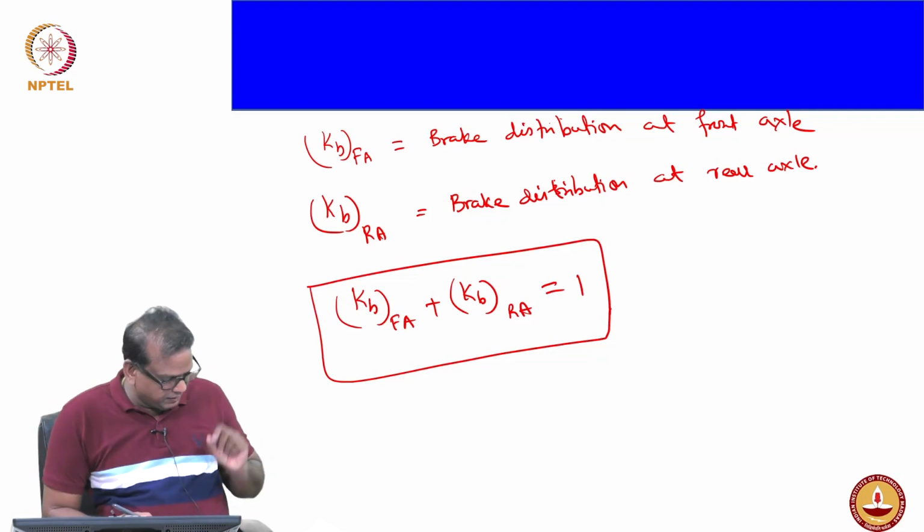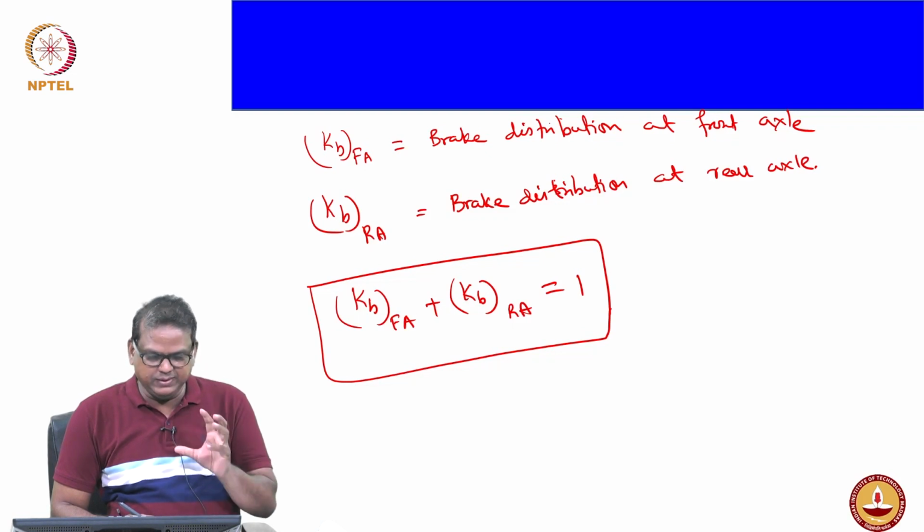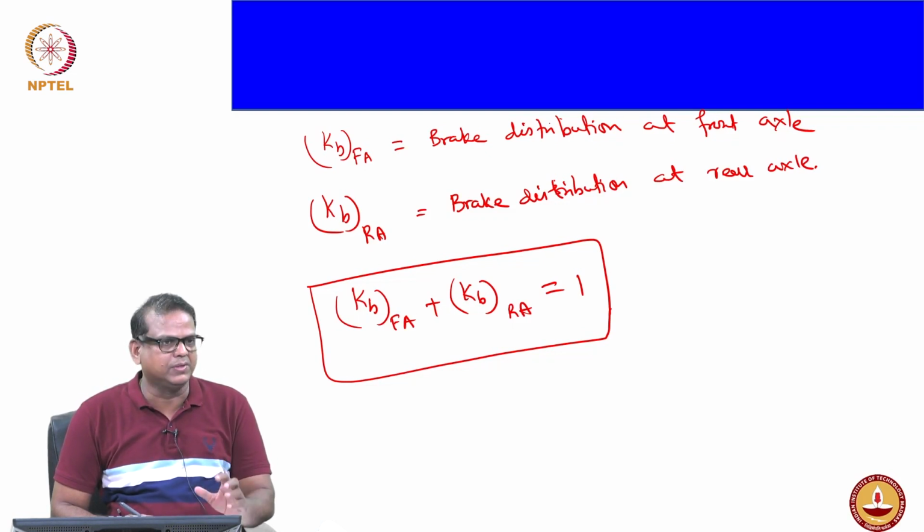And also we have discussed that the braking distribution depends upon the hydraulic pressure of the brake fluid as well as the wheel cylinder. Based on that, the proportion is determined. Whatever braking force or normal force is generated during braking must be balanced with the distribution which is happening in the hydraulic pressure as well as the wheel cylinder.